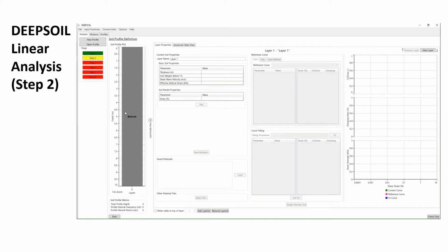Because this bedrock will represent, as explained in the lecture, all that section that goes underneath the superficial soil layers, any kind of clay, sand, or any kind of soil layer that you locate between the soil surface and the bedrock. And what the software is asking is, can you define the different soil layers at the top of that bedrock until it reaches the soil surface?